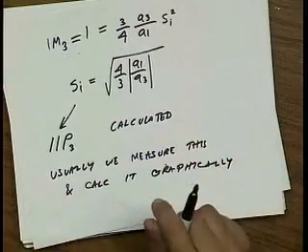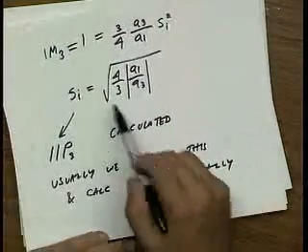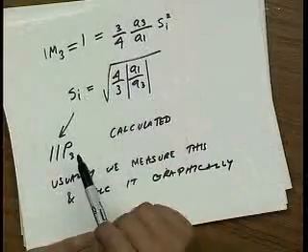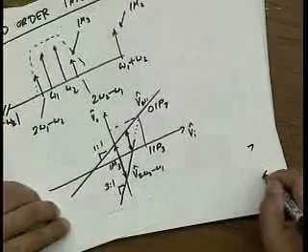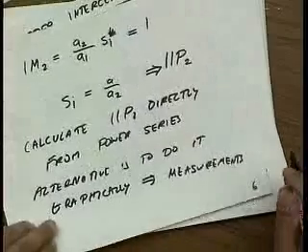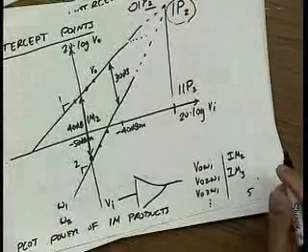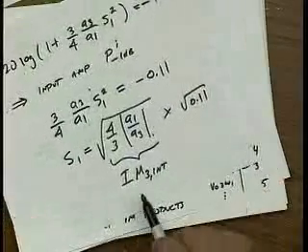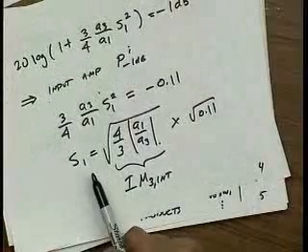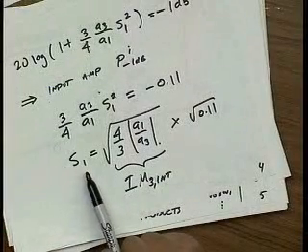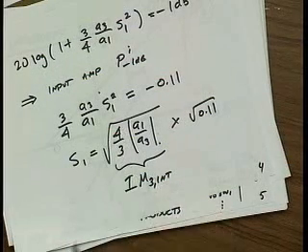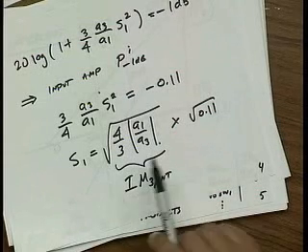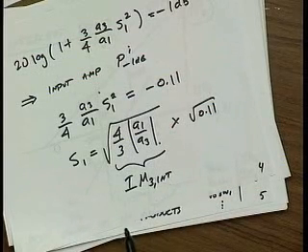that we discussed before. But what's interesting, what I want to point out to you guys, is this term in the square root, 4/3 A1 over A3. Let me go back a few slides. Look at the input that I need. What is this input power? This is the input power that corresponds to the gain dropping by 1 dB. It's also the square root of 4/3 A1 over A3. And that's why here I wrote down this is the IM3 intercept point.